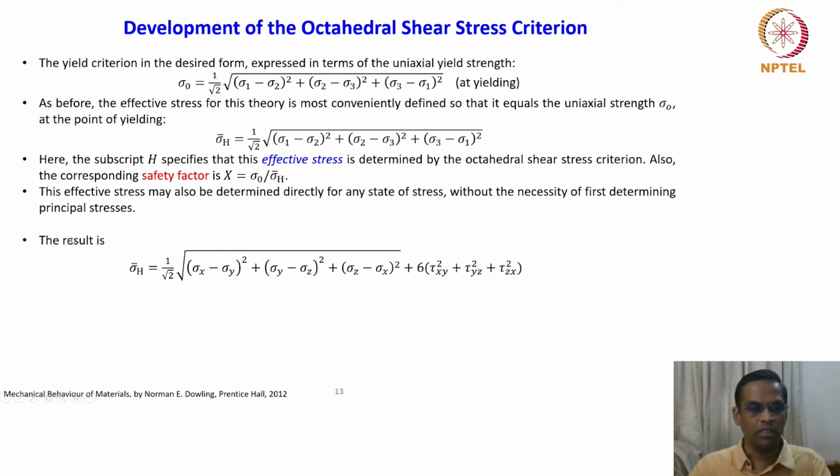So what is this expression? If you recall, when we opened up the stress matrix, we looked at all the invariants, stress invariants and strain invariants. If you go back to our old derivation, J1, J2, J3 are the three invariants we derived. If you look at J2, this expression is nothing but the J2 invariant, right?